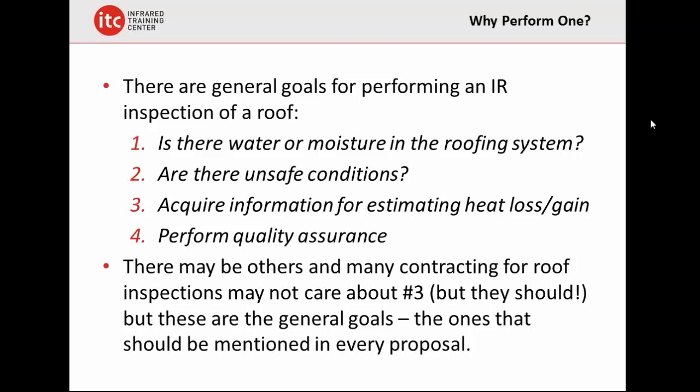The other thing here is watch out for unsafe conditions. There are many roofs that I've been on where we've stepped on the roof and it was kind of like walking on a trampoline. And we had one incident years ago where my registered roof consultant was going to take a core cut of a bitumen and gravel roof. He took his hammer, he took his chisel, he hit it twice, and the chisel disappeared. This chisel went right through the roof, and it disappeared into the building. The only thing that was supporting him was the layer of bitumen and gravel.